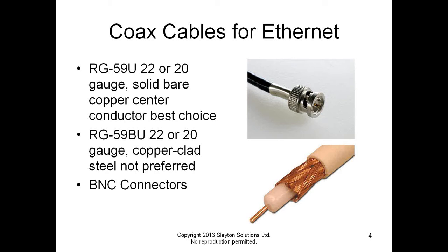What you see in the lower right-hand side is the basic construction of a coaxial cable. We've got that center conductor. You see it sticking out. It's copper-colored. Then we get the white stuff. It's called a dielectric, and that is a non-conducting element. It's usually a plastic. Around that is the shielding material. There are different grades of shielding: braided shielding, which you see illustrated here, foil shielding, screen shielding, and some vendors have what they call quad shielding, where they put all 4 types of shielding on their cable, and then there's an outside jacket.